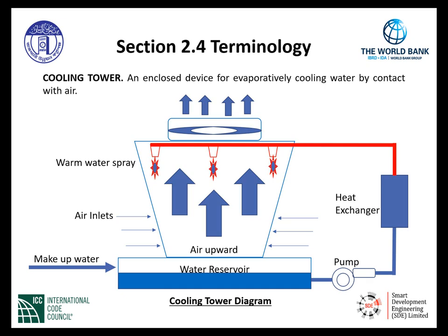Cooling tower. An enclosed device for evaporatively cooling water by contact with air. The cooling tower in the diagram below is as follows. As you can see, we have a water reservoir at the very bottom of the cooling tower. The water reservoir must be at a certain level to allow the pump to draw in water on the inlet